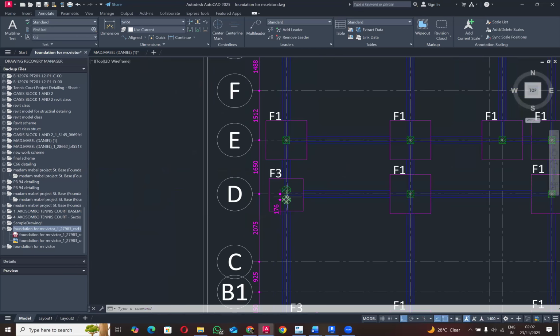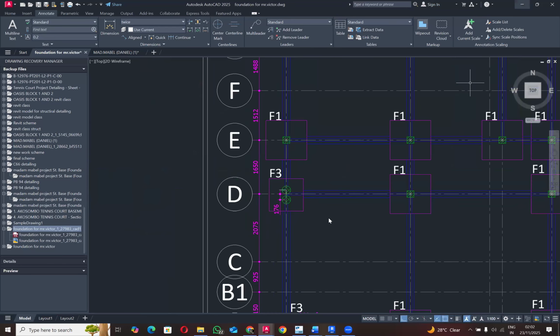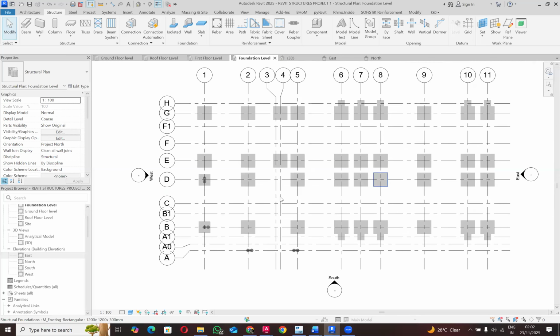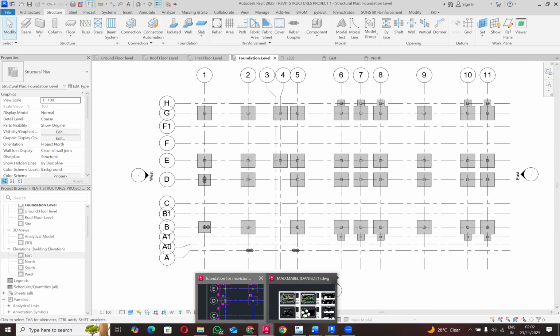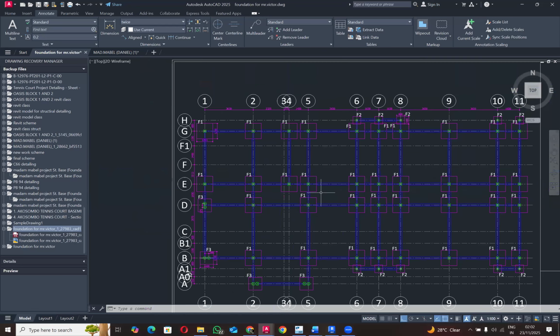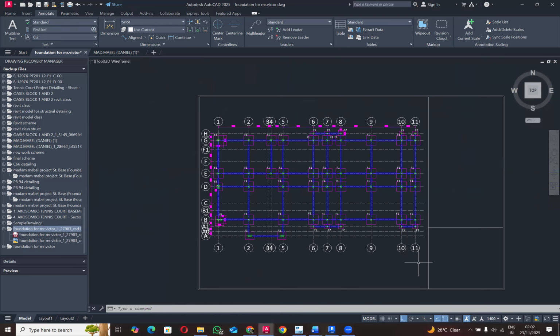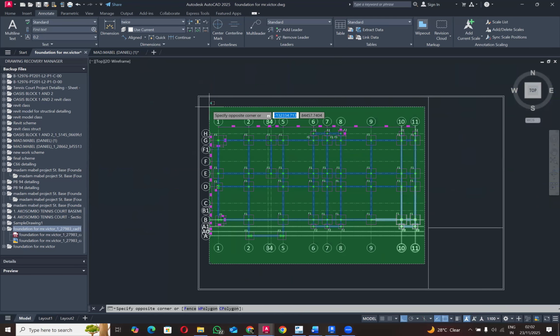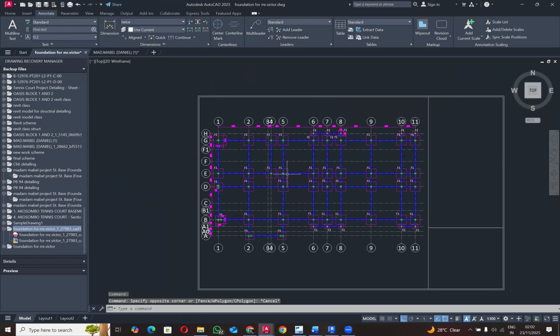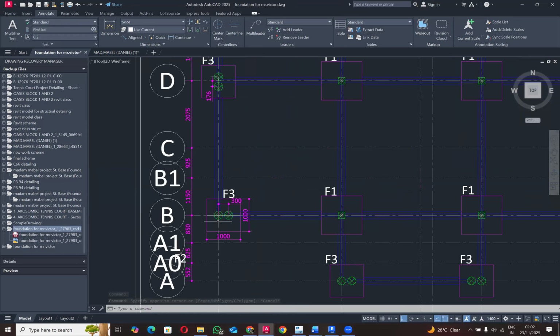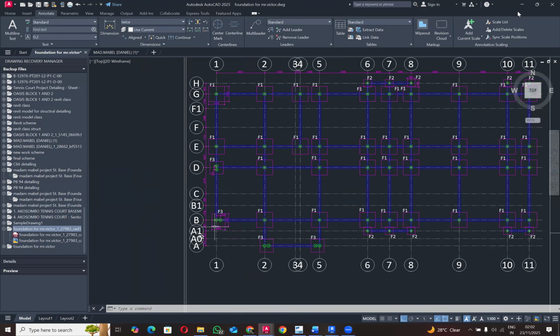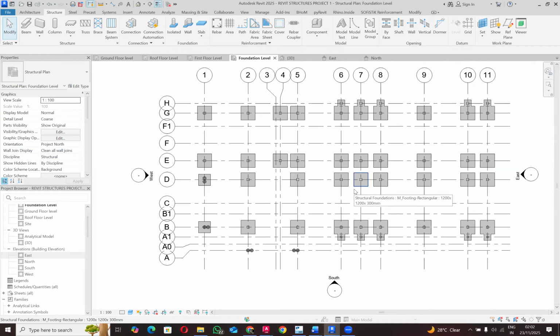So you see, there's another thing that you can also do if you don't want to be doing all this process. Because you already have your reference drawing here, you can import this file into Revit or create a link file of this into Revit and then do all the snapping directly. So there are various ways you can go about it to do this very, very fast.